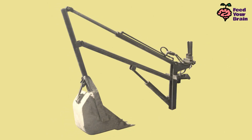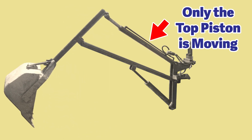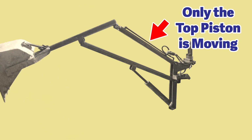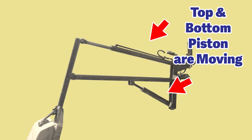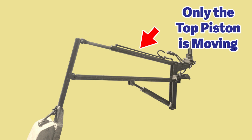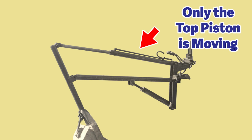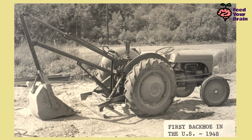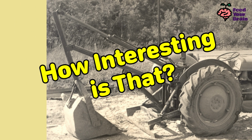Let's look at how this backhoe moves. First, here is just the top hydraulic piston moving in and out. You can see that only the arm and bucket move forward and backward. Now the bottom hydraulic piston will shorten, which means the entire backhoe arm and bucket will move down. Then in this down position, the bucket can move inward by the top hydraulic piston rod pushing out of its cylinder. And this is how a backhoe was built in 1948. How interesting is that?